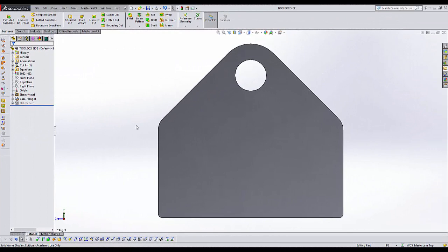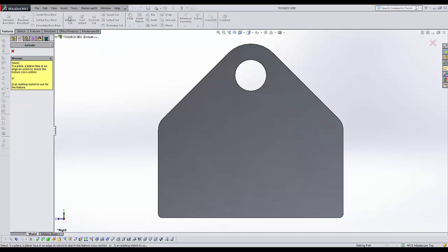Now let's start our drawing. Again, we can choose what we want to do. We know those holes are going to be used to cut through the part. So if I choose, rather than just a plain sketch, I can actually choose the feature I want to do. I want to cut, extruded cut.